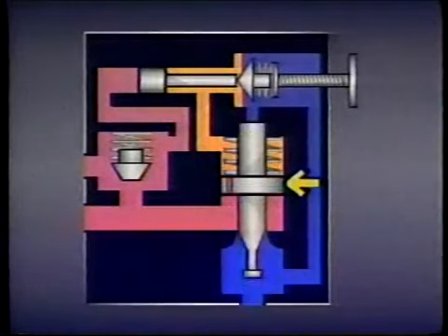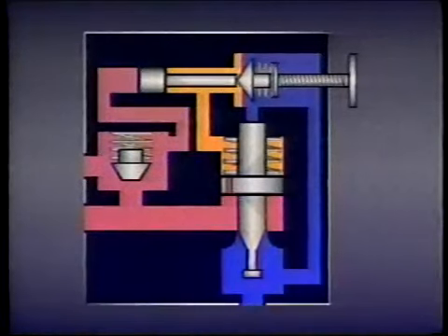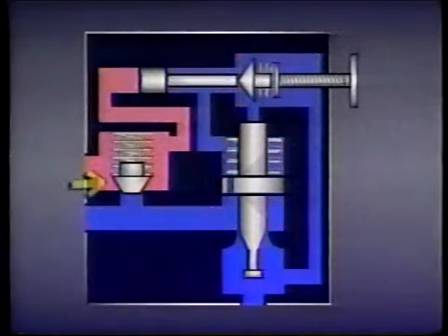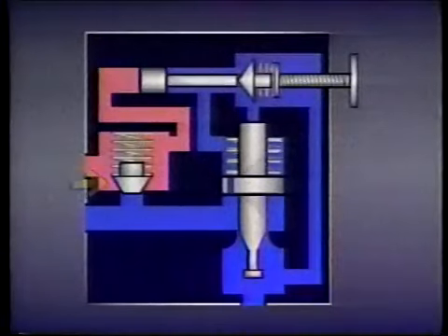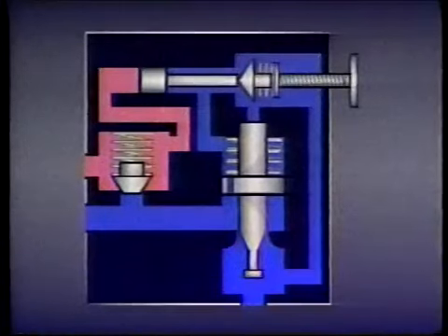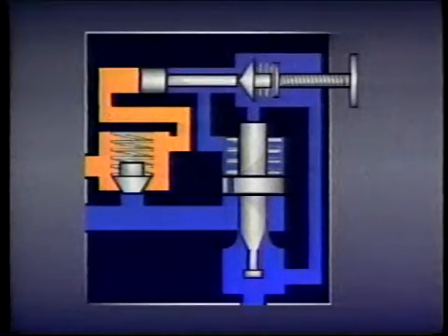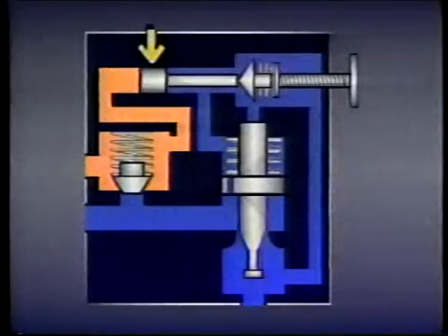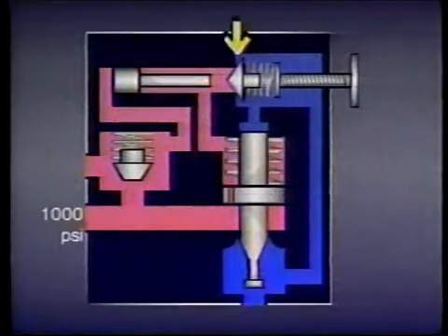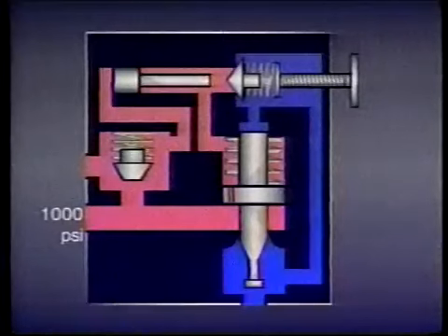The main valve spool shifts, opening a passage from the pump directly to tank. When that happens, inlet pressure drops, and the check valve closes, preventing the accumulator from discharging through the relief valve to tank. However, when the accumulator discharges enough fluid into the system that its pressure drops to 850 psi, the pressure on one side of the differential piston also drops. When this happens, the piston shifts back. The tension of the spring reseats the dart, and pressure begins rising again as the accumulator fills with fluid.